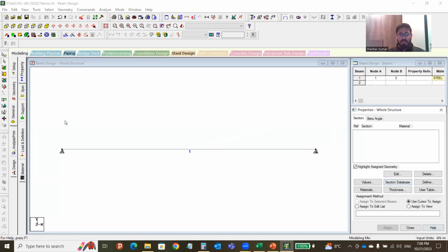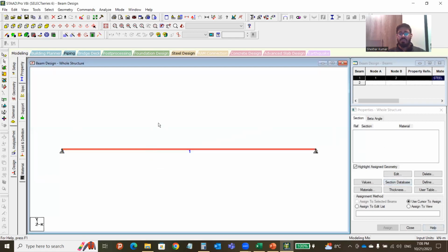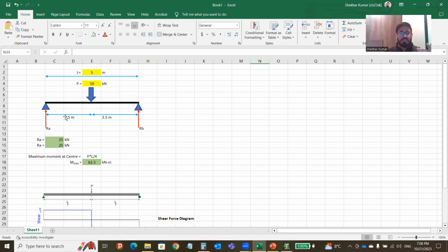Now go to property again. And if it is steel, we are aware of the member that is steel. But which section, which beam? Here we have not discussed any steel section, which section it is. Is it an I section, a box section, a square section, a solid or hollow or a circular section, an edge section, just a plate or just a wire? No, we have not. So let's assume that this is an I section. We will assume that this is a British I section.